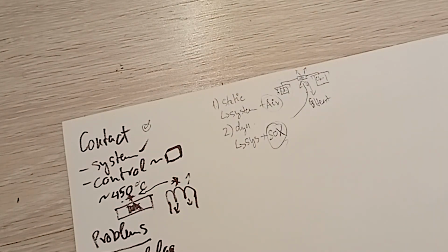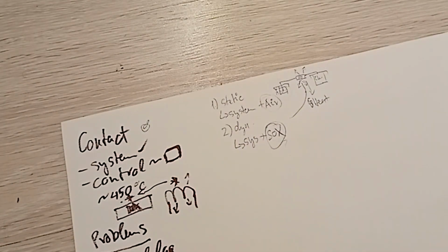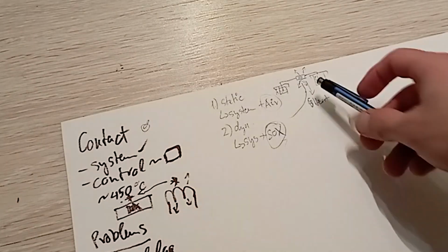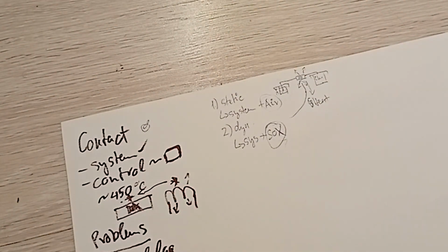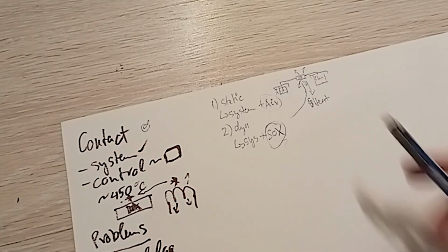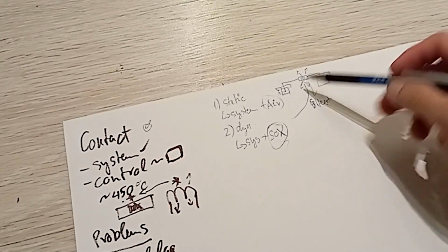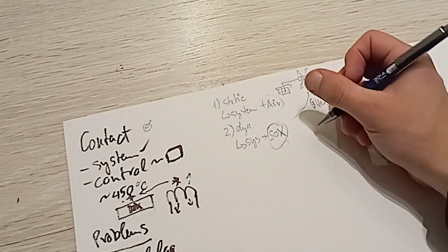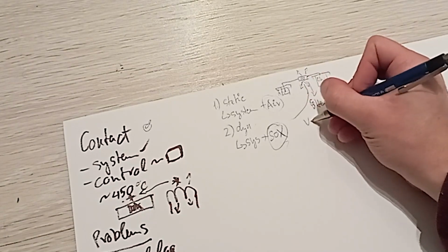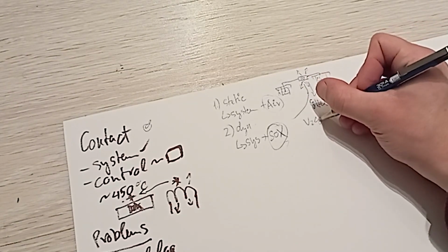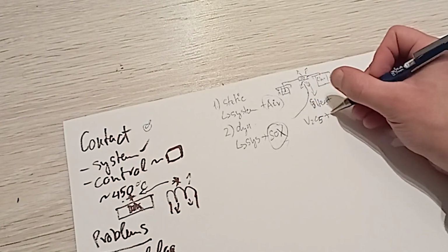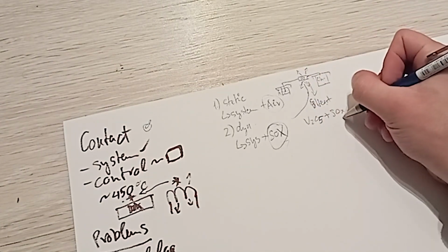If the humidity in the basement that I am working in changes, then so can the concentration of sulfur that I will be burning, even with the same conditions, given heat and all that stuff. So that can impact the heat generated from the sulfur reaction, the chemical reaction on the catalyst. So this is vanadium pentoxide, V2O5, plus the SOx, but mainly SO2.